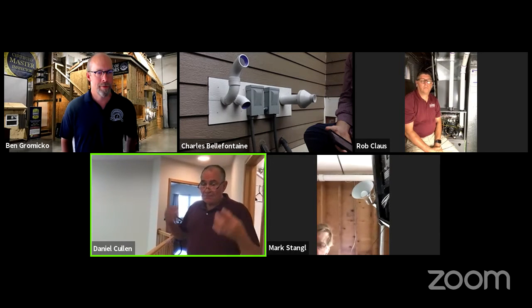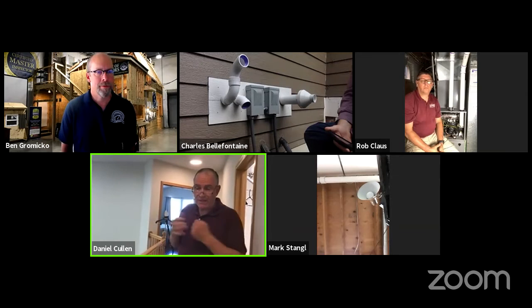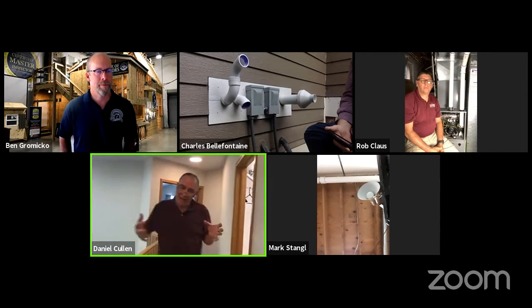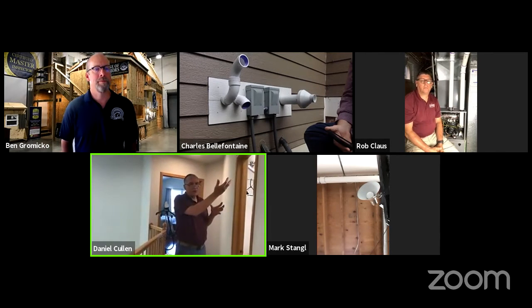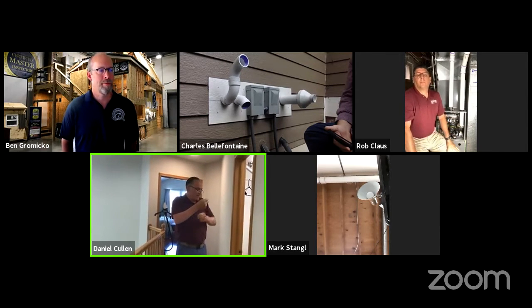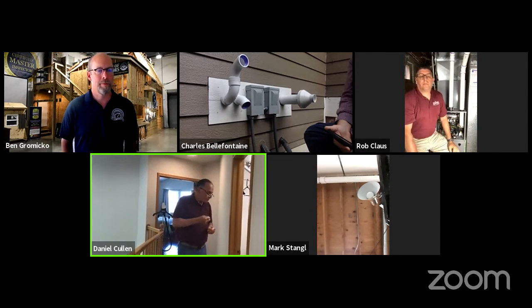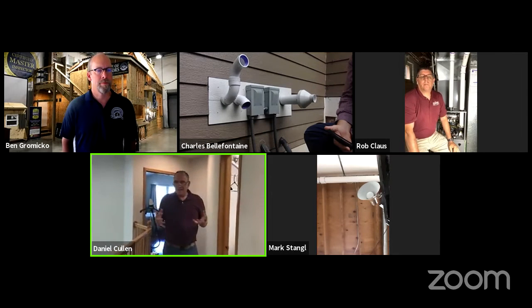If we oversize our air conditioners, we end up with a situation where it runs for a short period of time, gets the air very cold, satisfies our thermostat, but doesn't run long enough to pull what the HVAC contractors call latent heat, or humidity, out of the air. There's not enough contact time with our return air across the evaporator coil to wring that moisture out of the air.